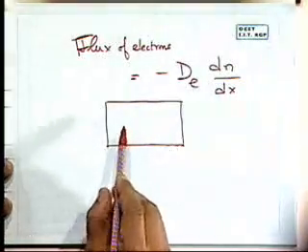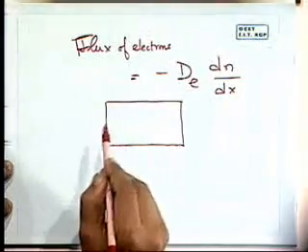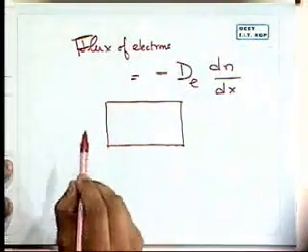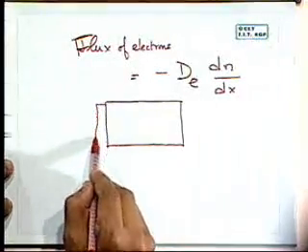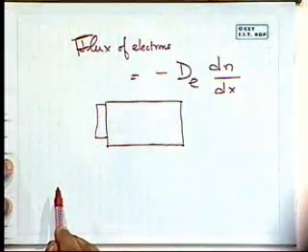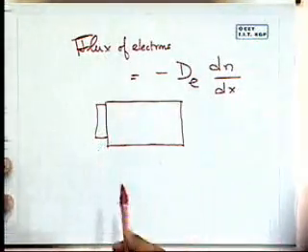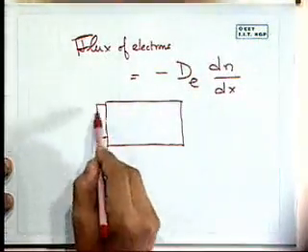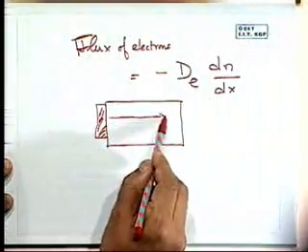One of the easy ways of introducing a dopant into a crystal, especially for crystals in which the particular species, the dopant, can diffuse fast, is to attach some solid which contains that dopant species to the silicon wafer and heat it up. And when you do, obviously there's a high concentration of whatever is in here and it starts diffusing in.